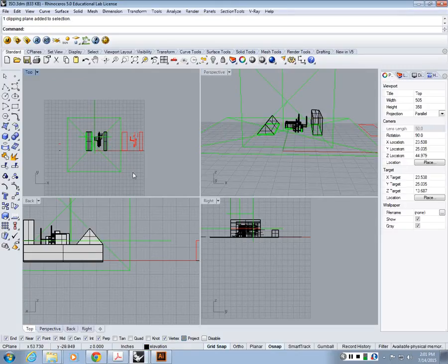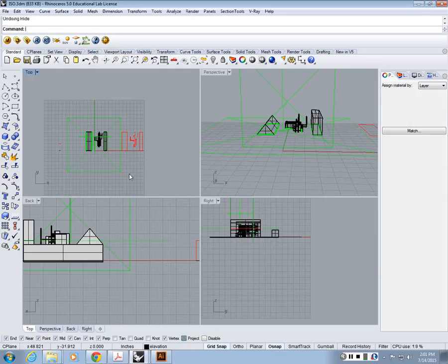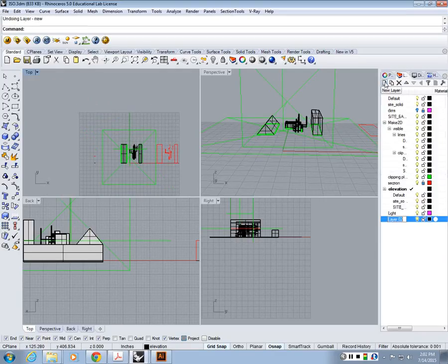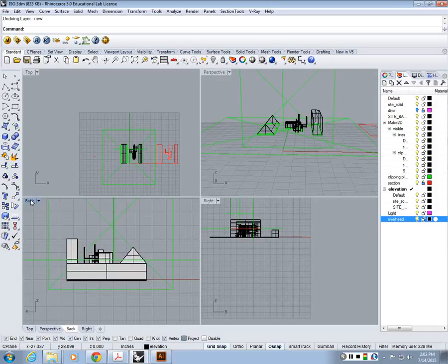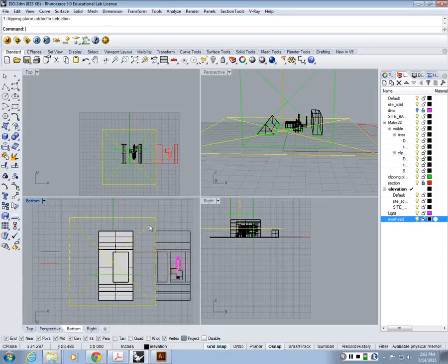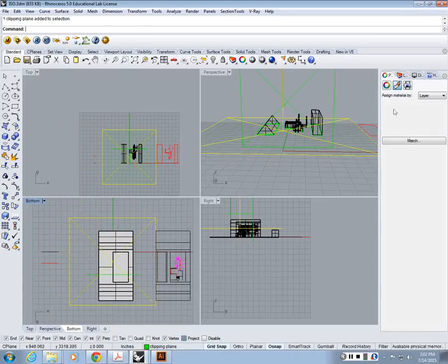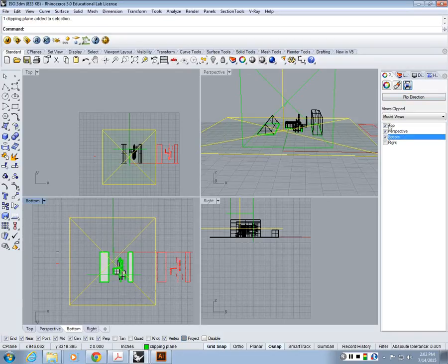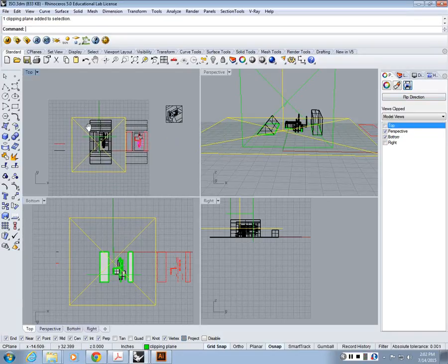Okay. So let's back up. I want to do Overhead, all right? I'm going to use the back here and then Set View to the bottom, choose the clipping plane, and under the active layers switch to bottom but deactivate top, right?